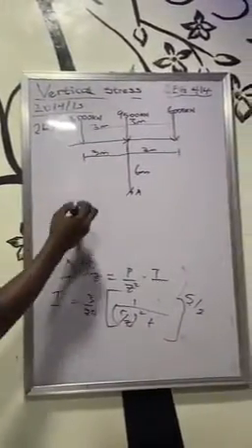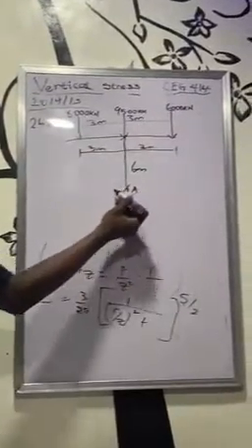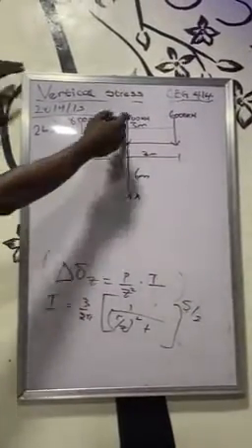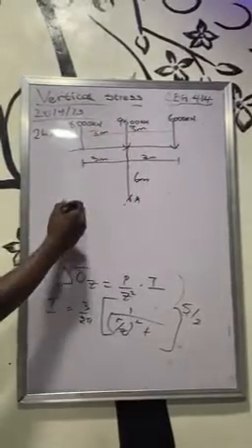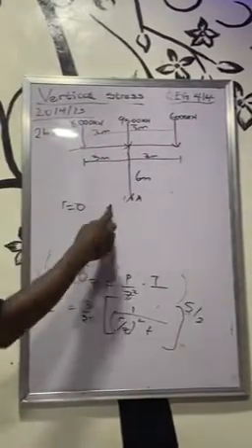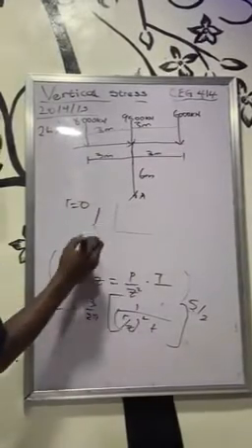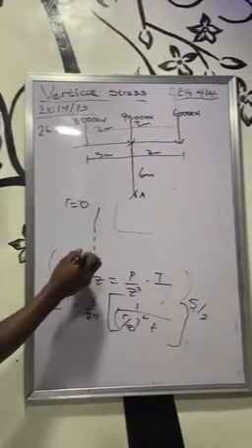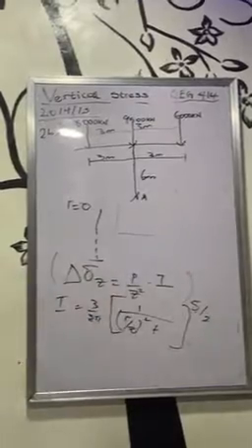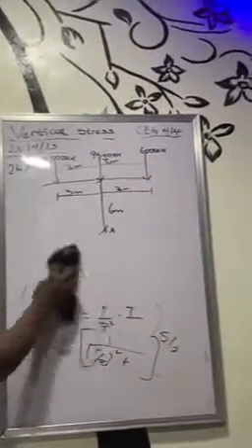For this 8,000, my R is going to be 3. For this 6,000, my R is going to be 3. I think you can guess that for this 9,500, R is going to be 0 because there's no perpendicular distance. It's like just taking moment, as I said before. Moment is the force and the perpendicular distance. For this point, there's no perpendicular distance. It's acting on the same line of action. So R is 0 for the 9,500 kilonewton. Let's move on.